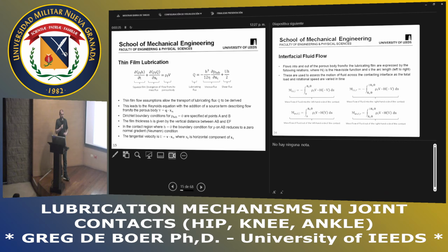Okay, so without any velocity, we wouldn't generate any pressure. But importantly, with this term switched on, we can solve for this P lubrication, P lub parameter, and then that couples back into our poroelastic model to provide the lubrication to the material.